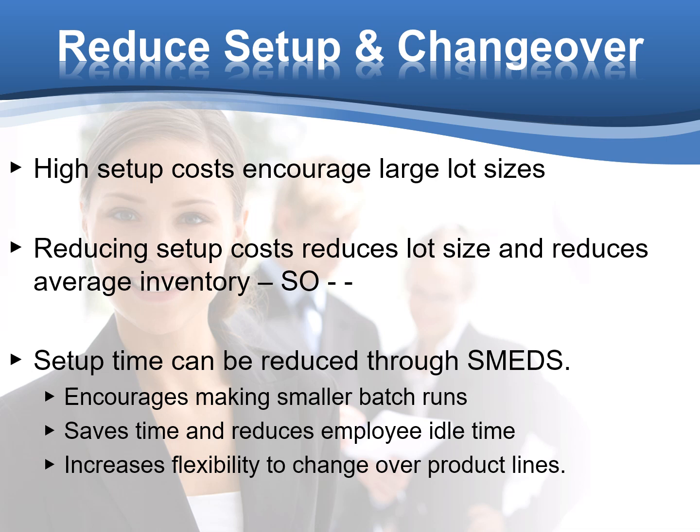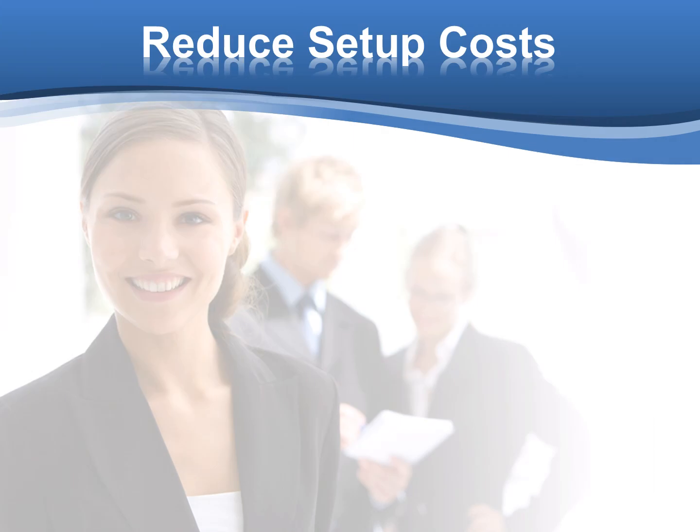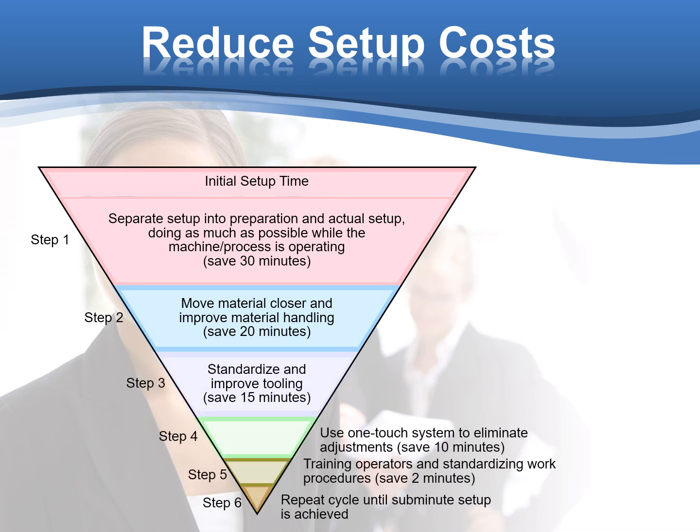SMED is single minute exchange of dies. It encourages making smaller batch runs, saves time and reduces employee idle time, and increases flexibility to change over product lines. SMED is merely a process of defining how quickly you can change over from one product to the next. So you can see here that the initial setup time might have been 90 minutes, but through using SMED, moving material closer, and improving your tooling and your setup tools, you can reduce your setup time to maybe 10 to 15 minutes versus 60 to 90.